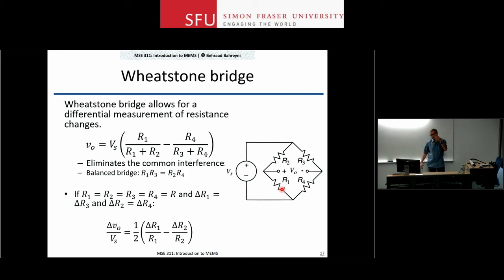You can also, we saw that when we talked about piezoresistors, that you have the longitudinal stress and the transverse stress on your piezoresistors. And the piezoresistive coefficients can be different, and actually in some cases one is positive, the other one is negative. So I can have a transverse piezoresistor here and a longitudinal one, and one of them will change in the positive direction with an applied stress, the other one will be changing in the opposite direction. I can get a bridge that way as well. Okay, so that is my resistive measurement techniques. Again, I kept it simple.